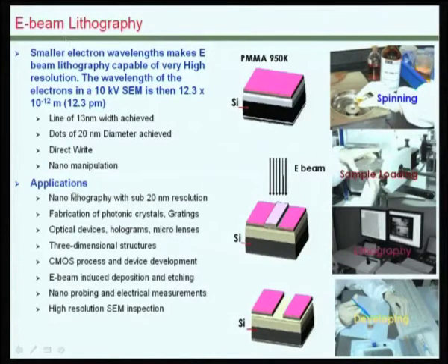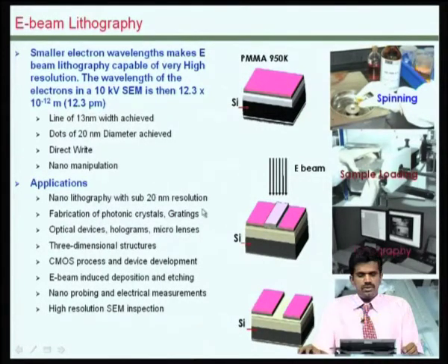The e-beam lithography has applications in nanolithography up to and even lower than 20 nanometer resolution, and it has significant applications in photonics, because these dimensions come close to the wavelengths that could be used and the gratings that could be created for various optical devices.